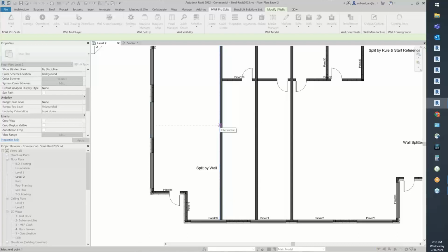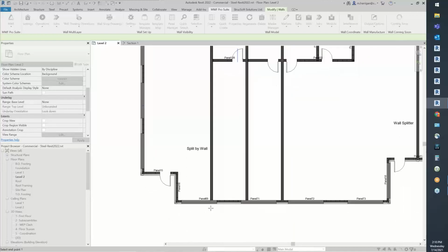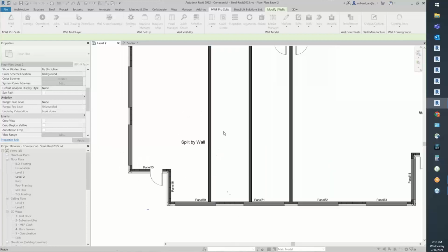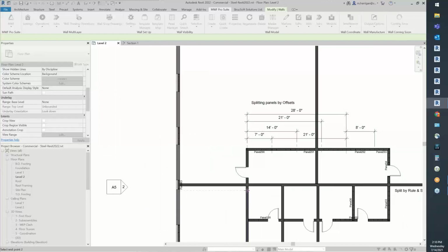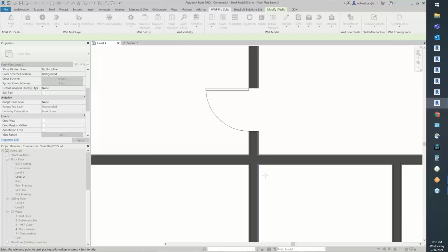That's going to ask you to select the points where you would like the walls to start from. So you can say from the endpoint of the physical wall to the endpoint of the other side of that wall. Or if you need to start a little bit in between, maybe a half an inch or so forth like that, again, you can put reference planes to know exactly where you need to. I'm just going to select this point here to this point over. Let's say we're going to start somewhere around here.